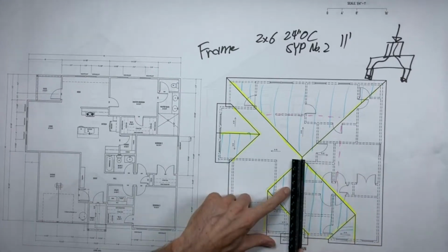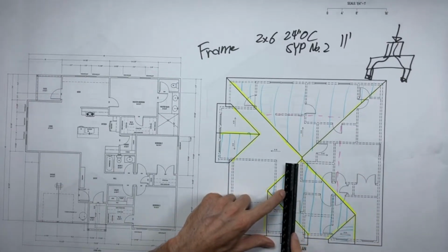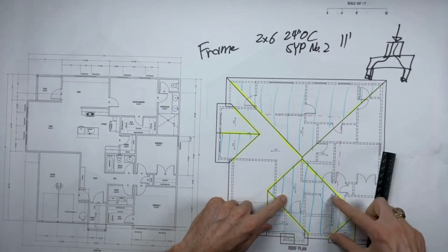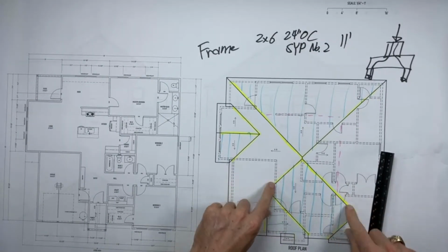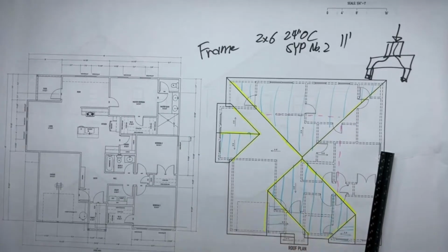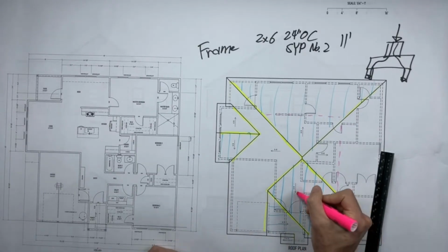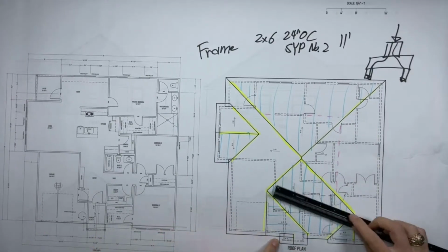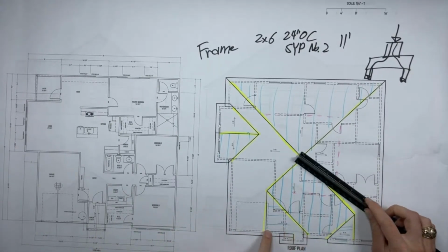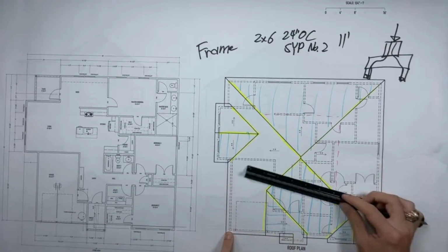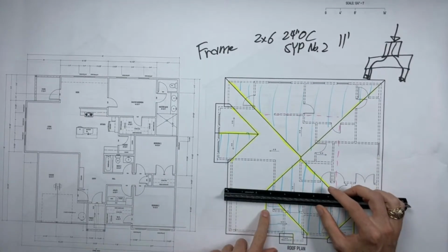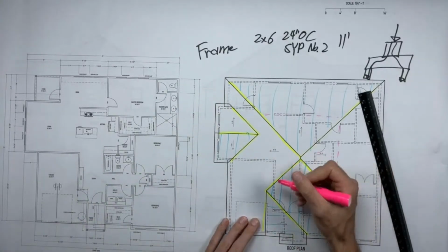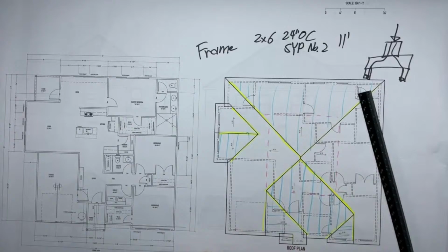But let's see, about right here and about right here are good spans. So we don't have to worry about these. So let's just put one in the middle and support about that middle area. That'll be good there. Let's check from this ridge down to here. That's 10 feet. So these are good. That means this side's good too, because it's right in the middle. That's 0 to 10 feet. So that means that probably right along this line is where I'm going to want to put one more. And that works out because I've got a wall.